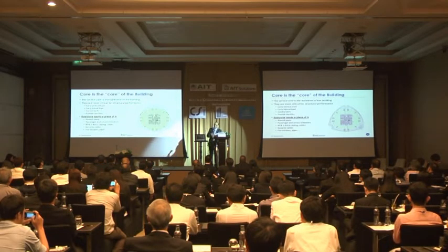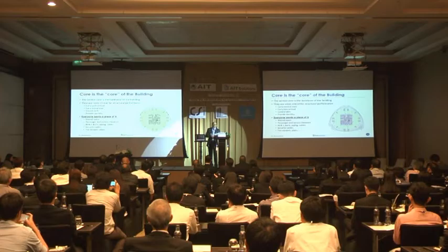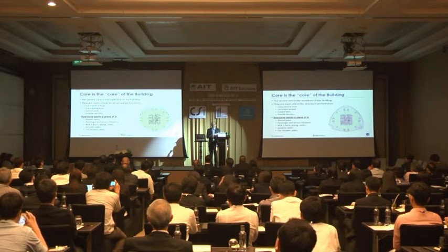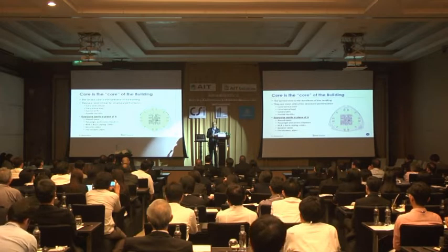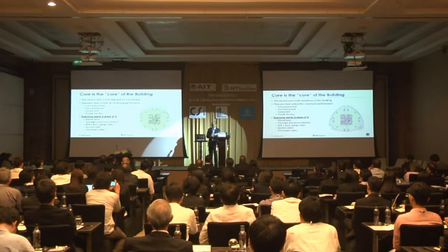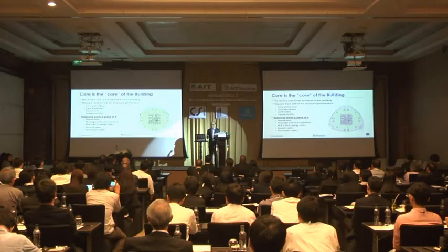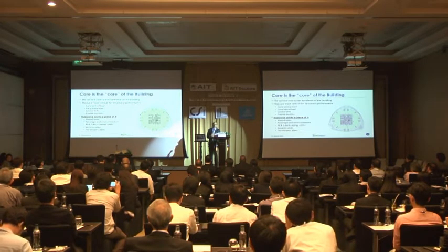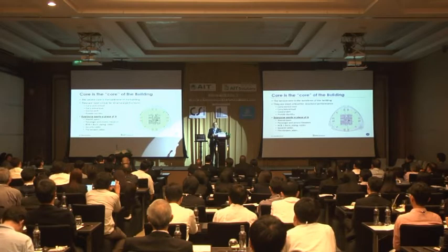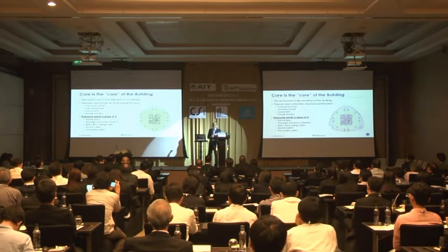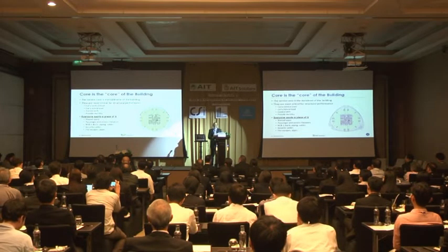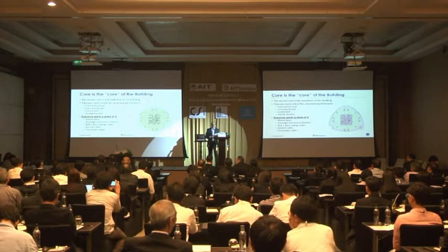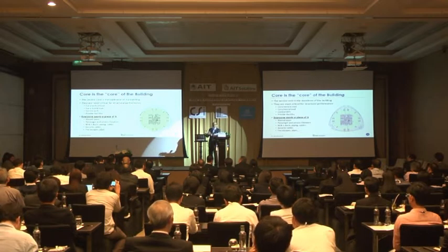And I remember, especially with Boise, every time they send a building to us for performance-based design, we almost always find one thing common. Vertical moment capacity is fine from the code. Shear capacity is underestimated by the code, so we want them to increase the shear strength of the walls. So the wall thickness needs to be increased, and as soon as we touch the core,